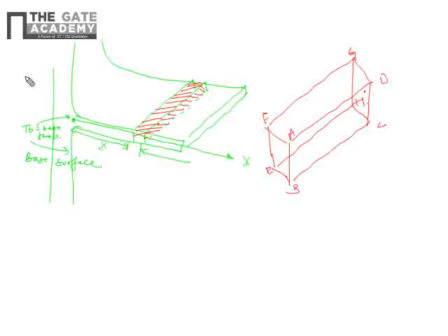If we see here, the convection can happen from the top surface, bottom surface and the two side surfaces. Now concentrate on the volume element. What will happen? Some amount of heat will come from the base via conduction at distance x, and from the cross section it will leave the volume element.